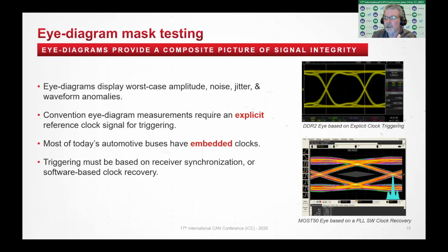And the recovered clock is based on where clocks are resynchronized, as well as based on the oscilloscope's much higher accuracy time base. And as I mentioned early on, this is a very common measurement on higher speed serial buses. Engineers really rely on this to give you an overall picture of the quality of your bus.